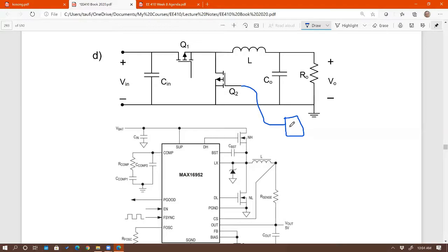Controlling the gate, you control the source. Yeah, the source you don't need to control because it's at a stable ground. It's basically 0 here. This is the gate. So you can send your PWM there, which is going to be relative to the ground. When the gate is high, that's high with respect to the ground, and that's going to turn on the MOSFET, assuming, of course, it's above the threshold. Good job. Does that make sense to you? Yeah, that makes sense. It's just a different way of notating or representing the PFETs than I'm used to. So thank you for the clarification.